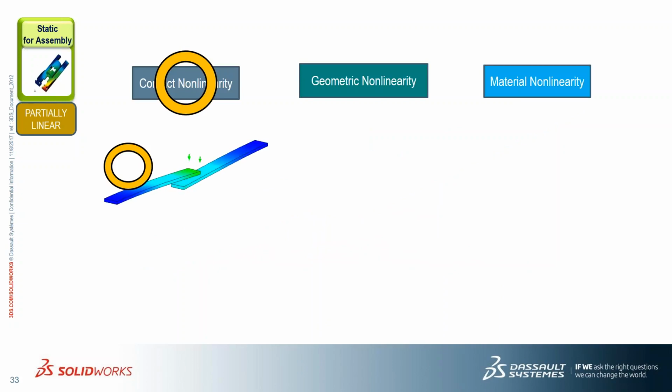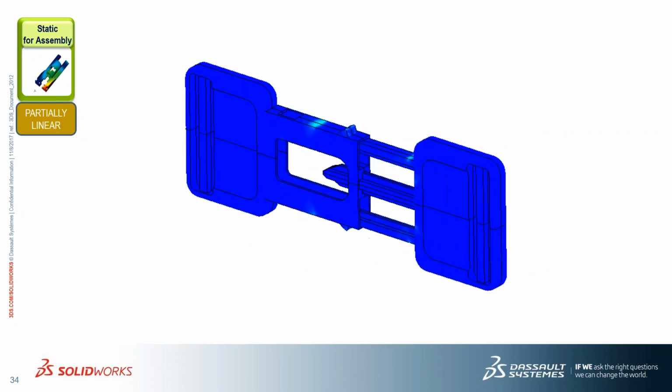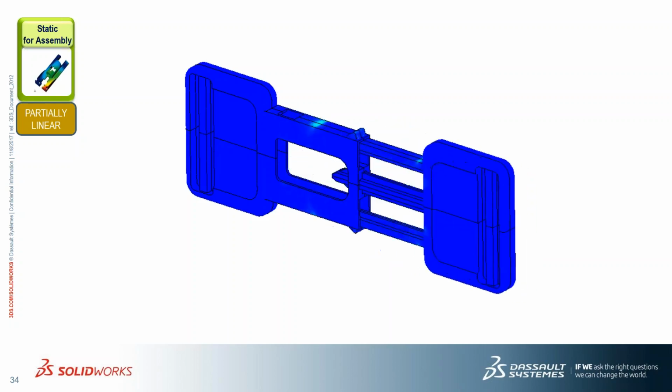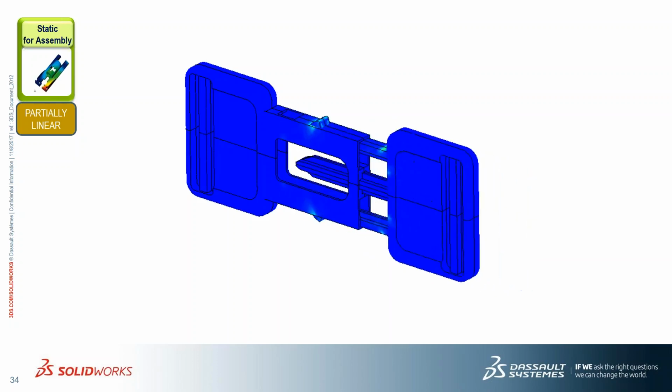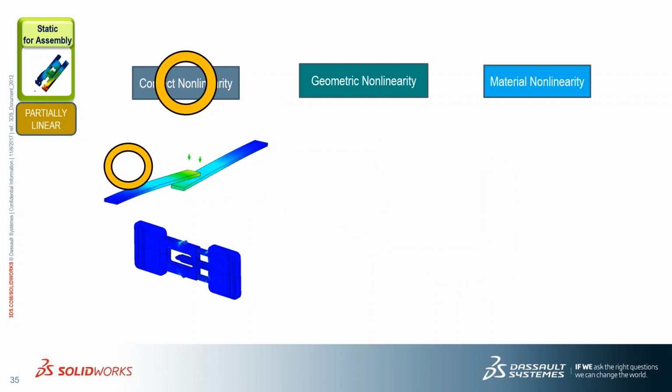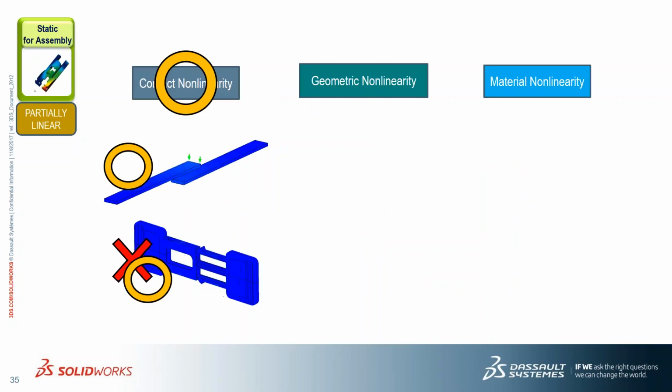So it kind of does the trick. It gives me the correct final answer, maybe, if that's all I'm interested in. But look at this one here. Again, it seems to predict the correct final position, but all those intermediate positions are sort of lost. And if my goal is to figure out the contact force required, it loses that result as well, because at the final position, the contact force should theoretically be close to 0. So there are some ways we can trick it to give the answer we're looking for, but it doesn't quite do the job. We can get it to work, but it will have to be a bit creative.